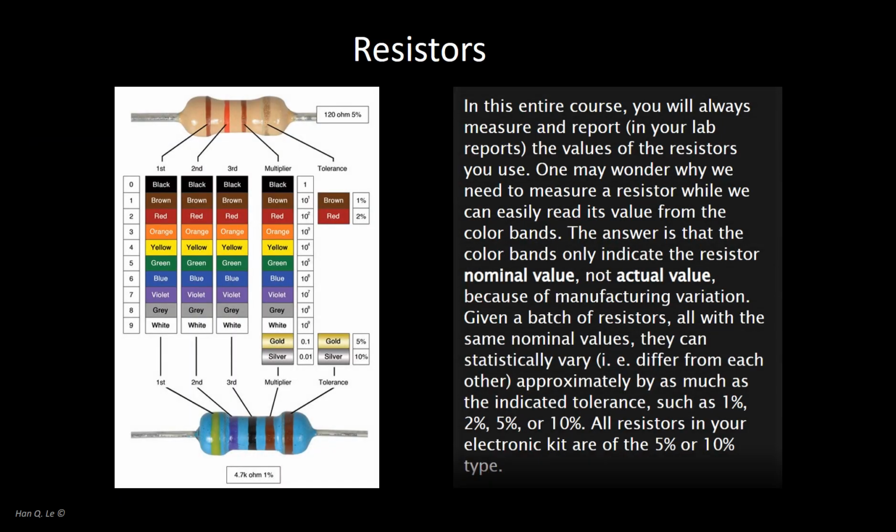There are many resistors in your kit. Some will be used in Lab 1. For a first-time user, use a reference color code chart to read your resistor nominal values. Then, use any digital multimeter shown previously to measure the actual resistance and verify.